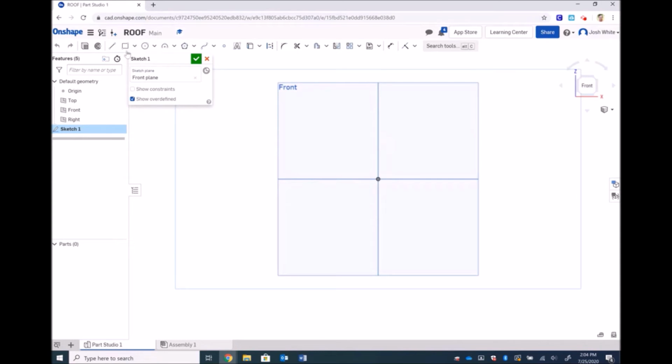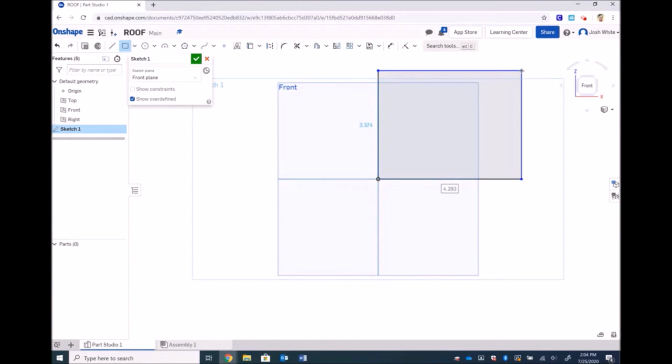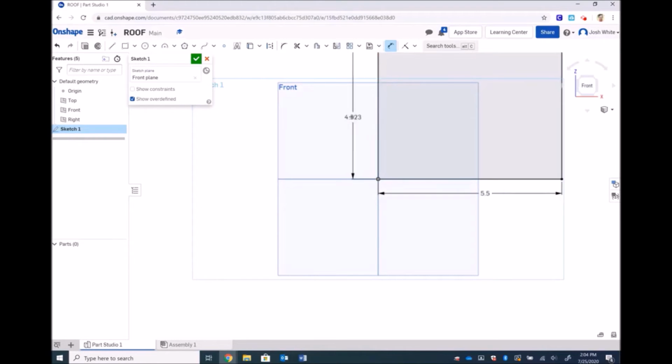and the overall geometry of our roof or top piece is again a rectangle. So let's make a rectangle from our origin. Oh no, now I don't have any dimension text boxes. That's okay. Let's dimension our bottom line to be 5.5 inches. Let's dimension any side, east or west, to be 7 inches.